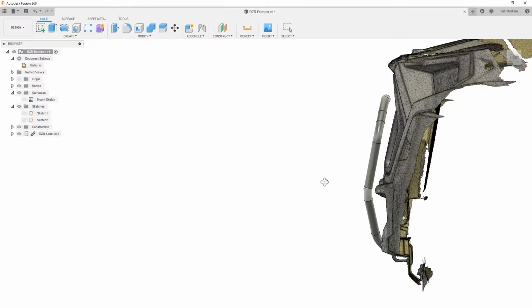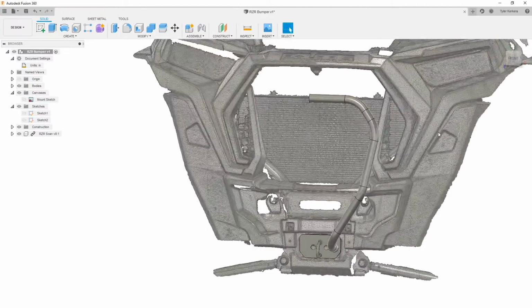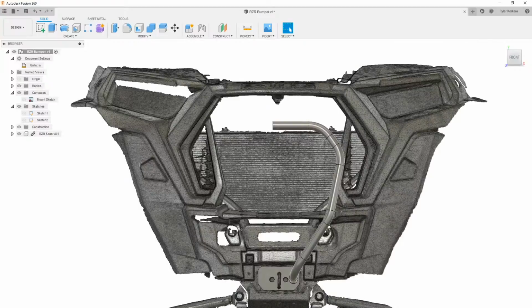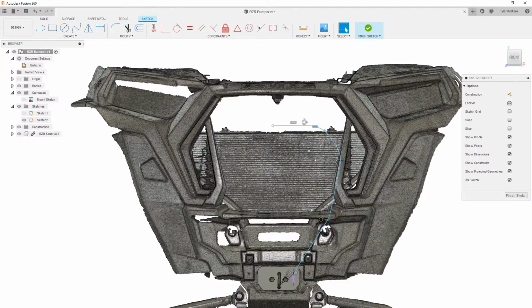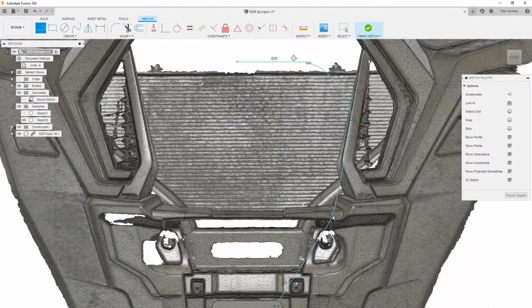That looks nice. All right, well, let's keep going with this then. So I'm going to go back into my sketch. Excellent thing with the timeline, right? I can go forward and start creating geometry, but I want to go back to that original sketch and continue adding to it. It's as easy as just double clicking on it. So from here, I'm going to add something like a crossbar so it can connect each edge.